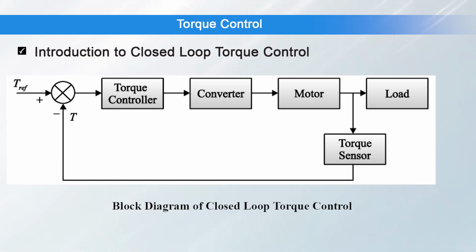For applications where a specified torque is needed regardless of motor speed, such as in line tensioning, the outer loop, which is a speed control loop, can be bypassed. Instead, a current reference signal is sent directly to the current controller through the torque reference terminal on the control board. Since torque is directly proportional to current, the current controller effectively acts as a torque controller. Adjustments for accelerating torque might be needed through a transient inertia compensating signal, typically managed via potentiometer or a digital